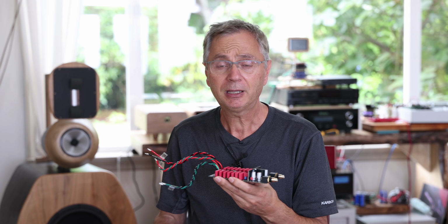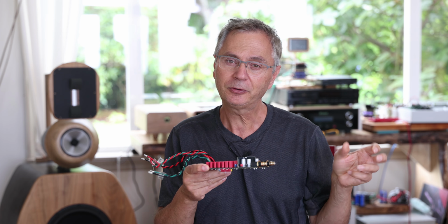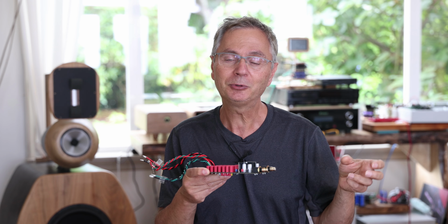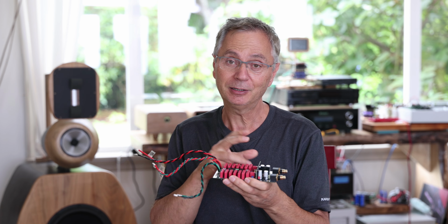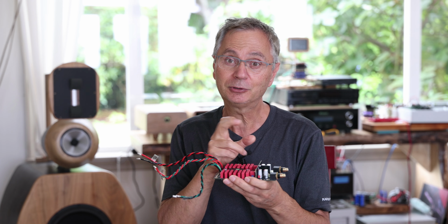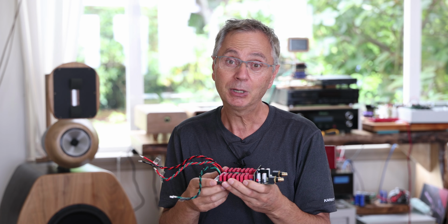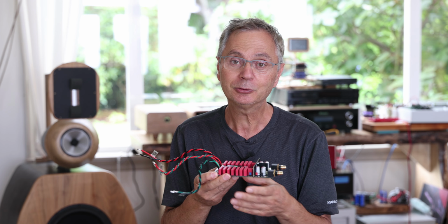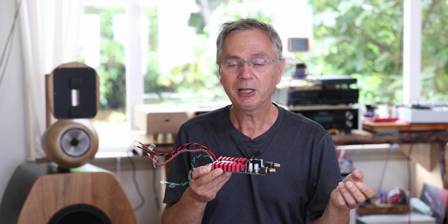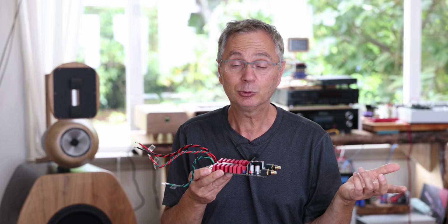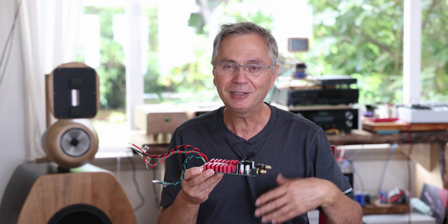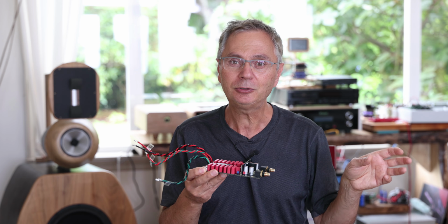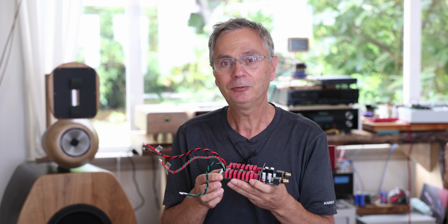And talking about that, make sure your speakers are set to a slightly lower volume. Don't crank them to the maximum and then plug the power in. You might get a DC voltage going in, and you might hear a big pop on your speaker, or it could damage your woofer. Most likely, it could damage maybe your tweeter or something. It's very unlikely, but I'm just giving you all the layers of safety, so put your volume a little bit lower before you power them.